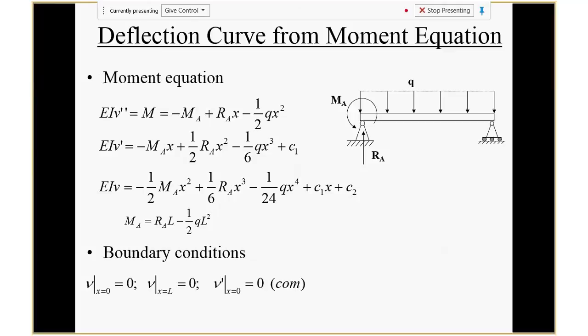Of course, you can also reduce it to a cantilever beam. That's another alternative approach. Let's say we use this approach, reducing it to a simple beam. Now, for this simple beam, can we solve for the deflection using the moment equation? Yes, we did that 2 or 3 lectures ago. So we find the moment. Is this the correct moment expression? It must be. Put it there.